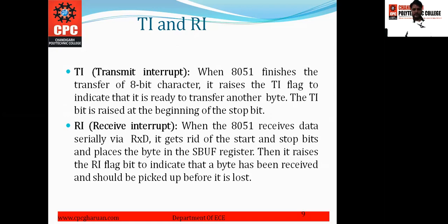Now the receive interrupt. When the 8051 receives data serially via RxD, it gets rid of the start and stop bits, because here we have to remove the start and stop bits to extract the data, and places the byte in the SBUF register, that is the actual data that we have extracted. Then it raises the RI flag bit to indicate that a byte has been received and should be picked up before it is lost.